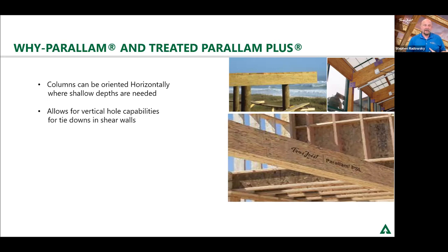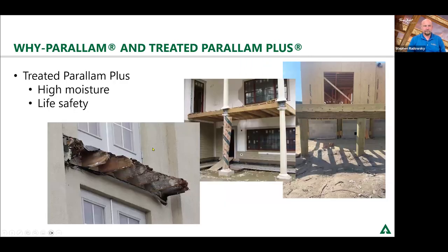The other great thing is that now, with shear walls in a lot of these large applications or in areas where base flood elevation and design elevations are required, you can actually drill holes through the vertical capacity of it in order to get that tie down from the foundation all the way up through your walls. So again, something to take a look at and know that it's possible when you have a single-sized member.